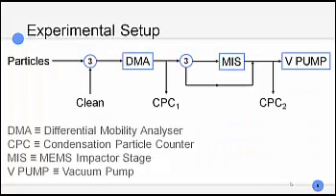From the experimental setup, which is really my focus, because I want to be able to test and characterize the different responses from the aerosol particles and the resonators. It's a relatively simple idea. So we have particles, and we send them towards a DMA, which is a differential mobility analyzer. And I apologize ahead of time for all the acronyms. But this is used to size particles. So it's based on the electric mobility of your aerosol.